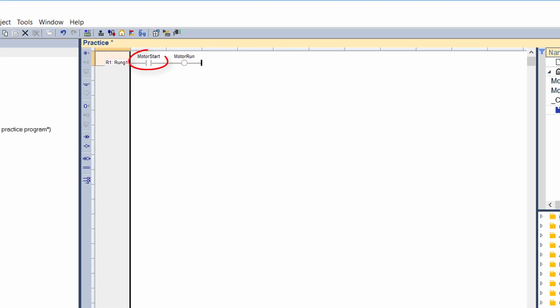The contact is a basic graphical element of the ladder language. A contact is associated with the Boolean variable attached to its graphic symbol. This variable is often, but not always, tied to a physical input point. If the contact is true, then power passes through it to the next part of the rung. There are 4 contact types in Workbench. You can change the contact type by highlighting it and pressing the space bar.